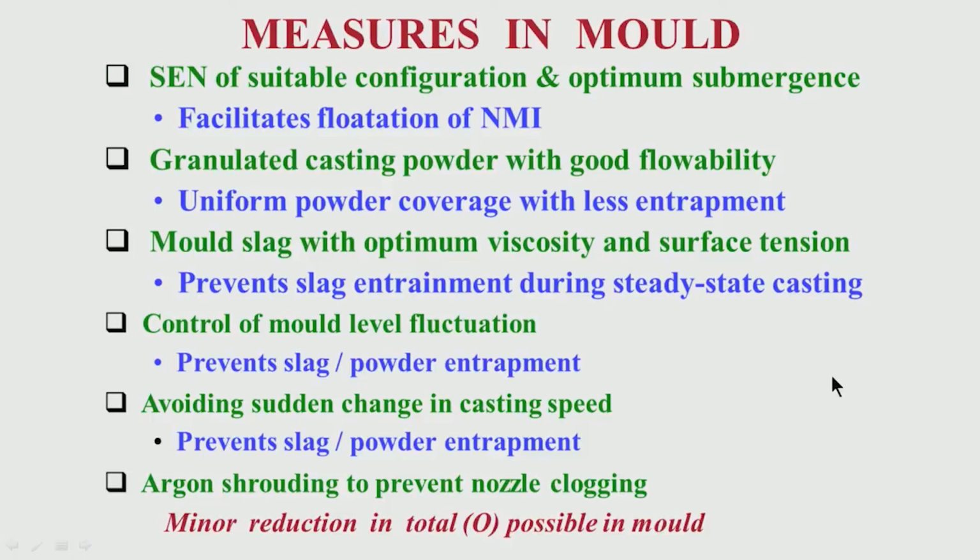Then a small amount of cleanliness enhancement we can do in mold also if we take a lot of care: if we do not allow any entrainment of liquid slag, if we use argon at the desirable flow so that there is no air ingress, if we do not allow too much change in the casting speed, too much turbulence we do not want. If you take all these measures, then some amount of enhanced cleanliness is also possible in mold.